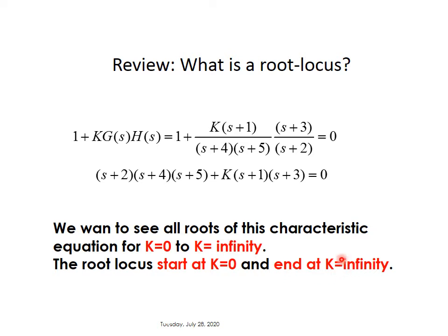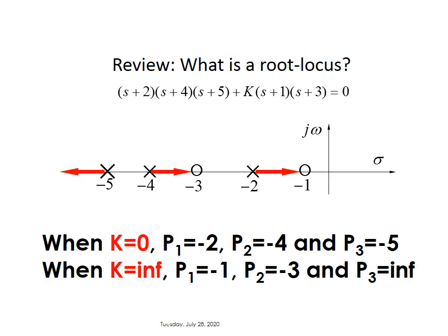So now I think we have reviewed enough of it, so we can tackle the sketching part. Okay, so let's take a look concretely at the application of the root locus on our previous system. So we put here again the characteristic equation of the system that we had in previous slides. So this is the characteristic equation. So what is root locus? It is basically plotting the position of the poles as k goes from 0 to infinity.